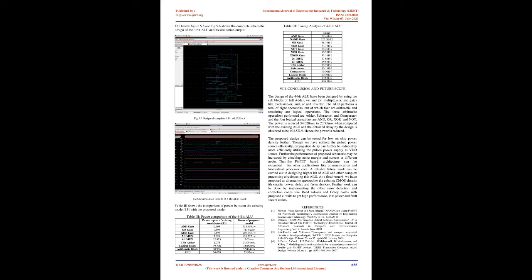4.6 Validation using adiabatic approach. Adiabatic circuits are low-power circuits that use reversible logic to conserve energy. Unlike traditional circuits that dissipate energy throughout the change, adiabatic circuits conserve charge by following 2 key rules. Never activate a transistor when there's a voltage potential between the source and drain. Never turn off a transistor once current is flowing through it. Adiabatic logic-based full adders have been proposed, and these can be compared with the XOR and the XNOR-based full adders. 4.6.1 Efficient Charge Recovery Logic, ECRL.